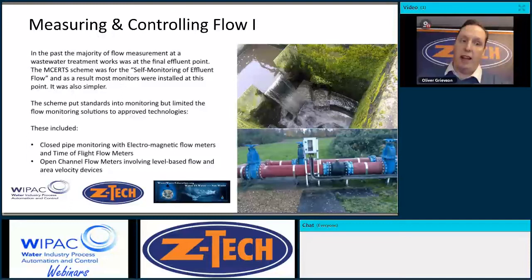And it was only in PR19 that the agency, through the WINEP programme and the water companies, have had the opportunity to really look at the works and look at flow management. And in the next AMP, AMP7, there's a huge amount of investment around FFT, around really, when we look at it, flow management, in preparation for, the last time I heard, 2026, flow becoming a regulated parameter with the same weight as the sanitary parameters.